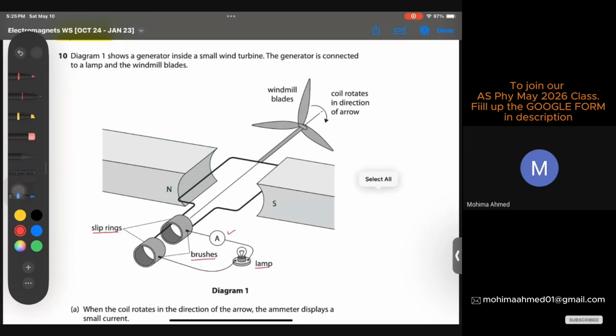So we understand that when that fan rotates, as the fan is connected to the coil, the coil will also rotate. And if the coil is rotating, then obviously there is flux linkage happening because the current carrying coil's magnetic field will be perpendicular to the magnetic field of your permanent magnet, and therefore because of this flux linkage, a voltage will be induced in this circuit.